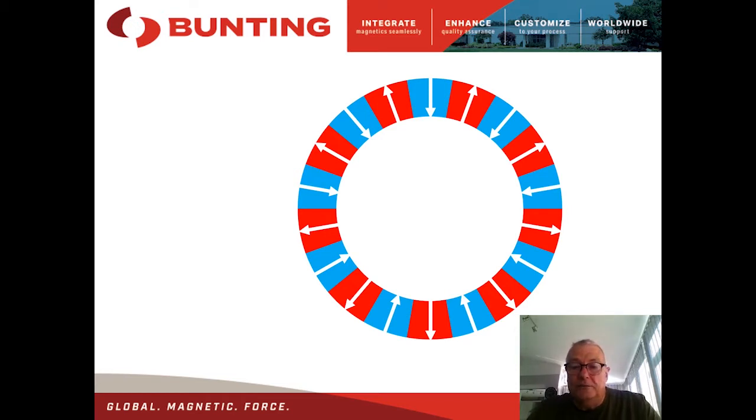They all follow the same basic principle, but there are different design quirks according to individual manufacturer's preference. So what we start with, and the working part of the eddy current, is really a rotor which contains rare earth magnetic materials. These are neodymium boron iron magnets, and they are set in a north-south configuration around the rotor. So we're going north, south, north, south, north, south, all around the outside of this rotor.